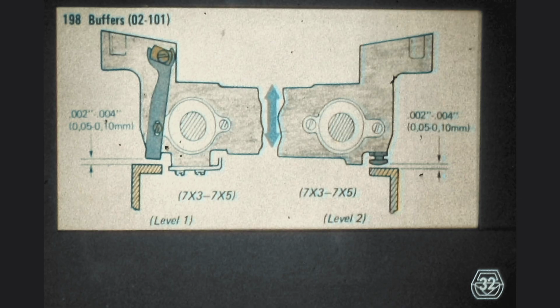We saw earlier that this learning program is divided into 3 sections. The first is printing, the second is alignment, and the third is character selection. With the adjustment of the carrier support rail, we have concluded the printing adjustments of our machine. The reason the carrier support rail has something to do with printing lies in the fact that the action of causing the rocker, which supports the element, to fly against the paper is met by a counteraction, or reaction, on the part of the carrier trying to rotate its front end downward. To prevent the carrier from changing its position due to a bow in the print shaft, we have adjusted the clearance between the carrier support bail and the carrier.